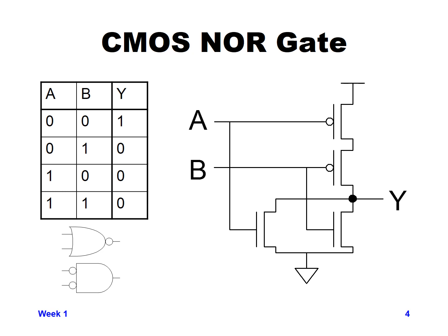So you have the first PMOS transistor, its source is connected to VDD, the top one, and then its drain is connected to the source of the lower level PMOS transistor, and that PMOS transistor's drain is connected to the output signal Y. That is also connected to the drains of both NMOS transistors, which are connected in parallel to the output, and the source of each of those NMOS transistors is connected in parallel with each other to ground.